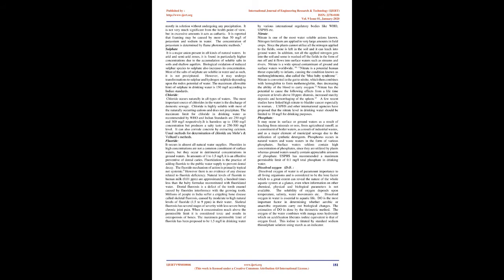Potassium. The concentration of potassium in most drinking waters is trivial. It has a similar chemistry like sodium and remains mostly in solution without undergoing any precipitation. It is not very significant from the health point of view, but in excessive amounts it acts as cathartic. It is reported that foaming may be caused by more than 50 mg/L of potassium and sodium in water. The concentration of potassium is determined by flame photometric methods.